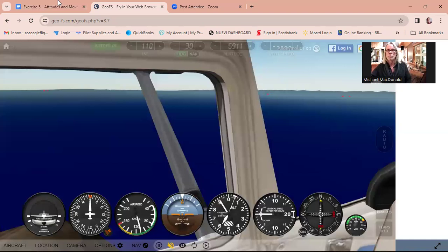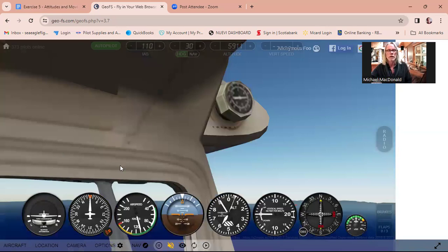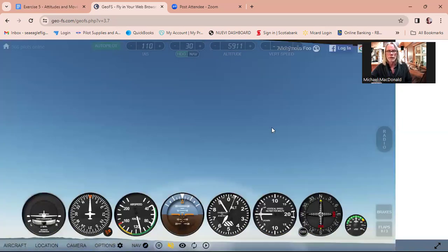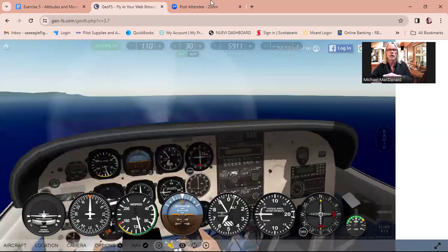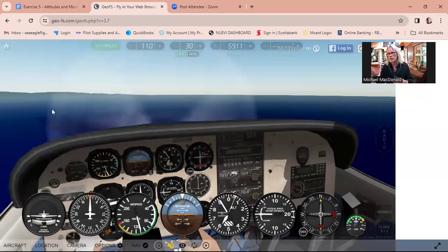Okay, the yaw is basically, let's get looking out the front of the window here. Oops, that's the back. The yaw is basically around that normal axis, the up-down axis, right? The yaw basically skews the airplane with only a slight bank, because it's done with pedals, right? Every time you use the pedals, the airplane will yaw, and it will induce a bit of a bank, but mostly that's not why we use the pedals. The pedals are used to coordinate a turn, which is a future lesson, which we won't talk about right now. But suffice it to say that the airplane yaws around the normal axis, okay, the up-down axis.